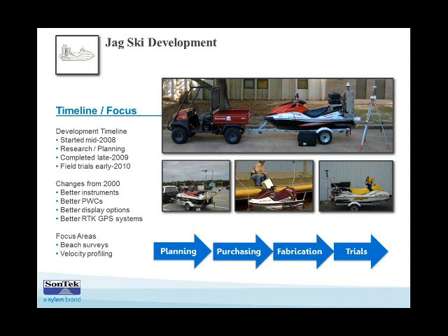And it's the larger case that's on the back of the personal watercraft, the kit that's vertically oriented. It's got a cable coming out of the top. Just a large Pelican case with multi-parameters on the inside and a pump and some standalone computer and telemetry and GPS unit. So we get 9 water quality parameters out of that. It's got a flow-through system and a pickup that works really well. Still use it today, and we used it after the oil spill to map hydrocarbon concentrations. It's got a fluorometer in it as well for doing crude oil and refined fuels.